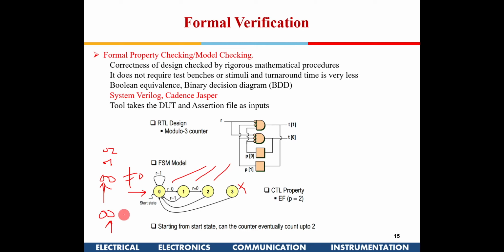You might be missing some information, right? Instead of that, you check for 0 0, then see in the next clock it is a non-zero value, and then check that after 3 clocks it becomes 0 0 again. In a microprocessor, if you keep loading that data, there is a zero flag that would come up. So you can see that. This is just a modulo 3 counter. It could be a modulo 65 counter or a modulo 120 counter.